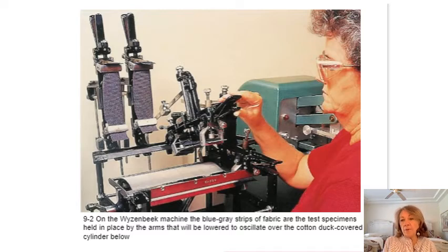by using perhaps a fine mesh wire screen, or they'll sometimes use a cotton duck, because abrasion on upholstery material is usually caused by human clothing, not by wire mesh. And the results are measured according to double rubs or oscillations back and forth. So it can be tested 1,000 times, 1,000 double rubs, or 500 double rubs.